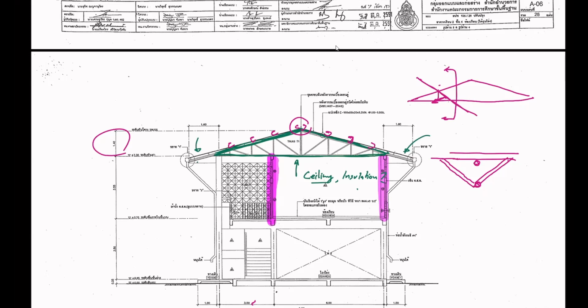Live load generally reflects the occupancy, or how you are going to use your structure, just like the live load in a classroom, for example. So where is the live load on the roof really? Construction workers, yes, which are not there anymore. They're only there during construction, and after that, it's all empty. So you have a roof with no load, but we designed every member to withstand the live load, say 50 kilograms per square meter. So even with bad construction like that, the roof will not fail because the load is not there.